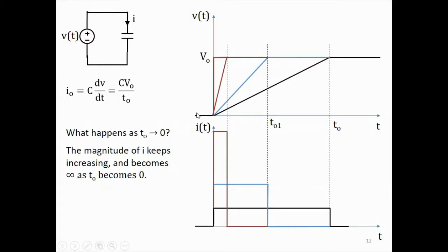All right. So if the voltage across a capacitor changes instantaneously, what that means is that we are supplying it a finite amount of charge CV0 in 0 time. And if a finite amount of charge has to be supplied in 0 time, an infinite current must flow.